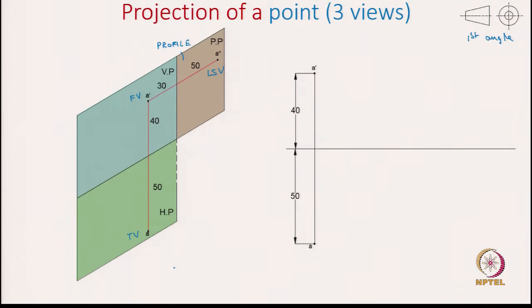Now, for us to draw the side view, we will again draw a second reference line which is perpendicular to the initial line. So, this again is a reference line, which is perpendicular to the other reference line, and we use a technique where we can capture the dimensions in the top view which will help us to draw the side view.